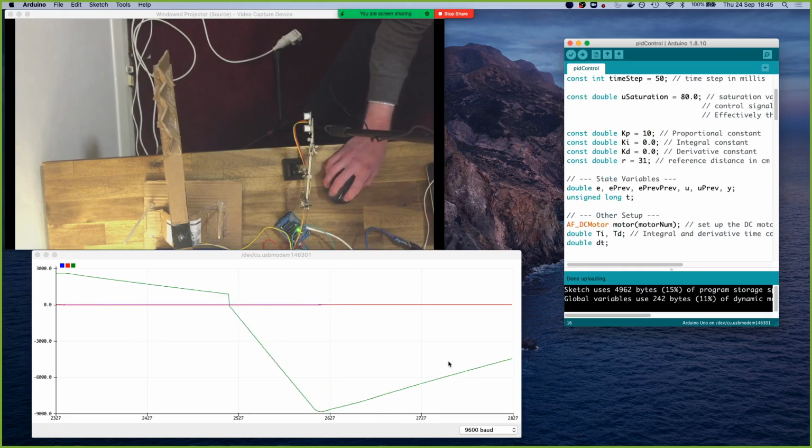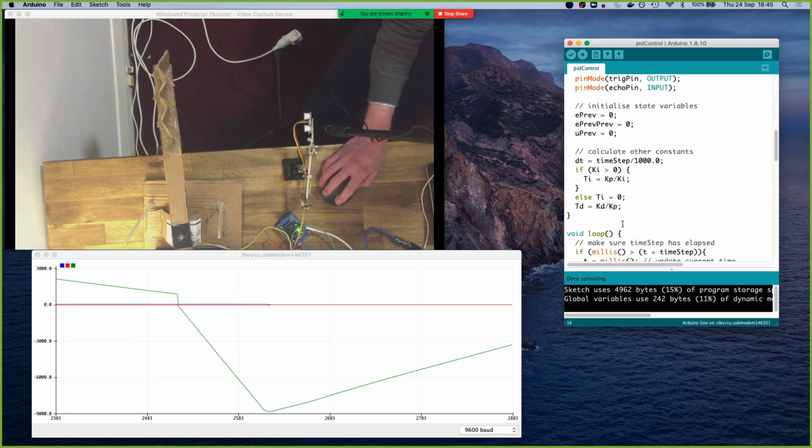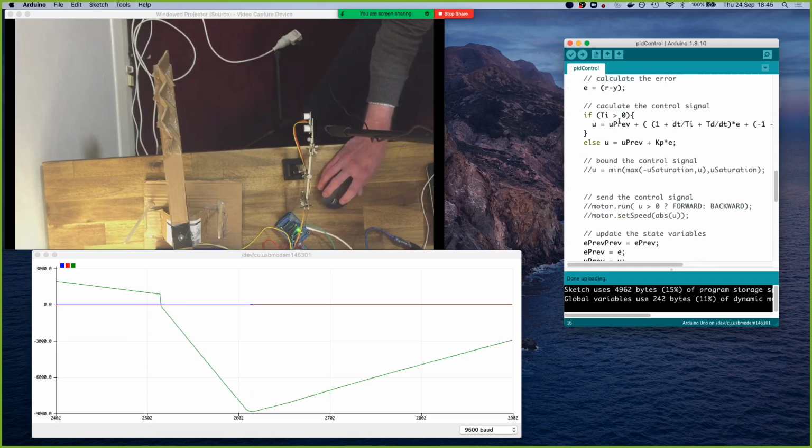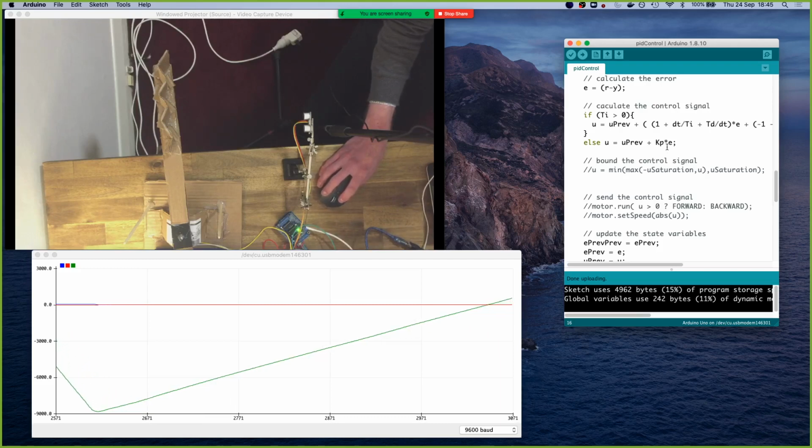This is something referred to as integral windup. And that's got to do purely with the discrete realization of this controller, and the way that it's implemented. The naive, yeah, tracking the previous state, so it keeps growing based on the fact that there's still an error. It's a little bit hard to explain.